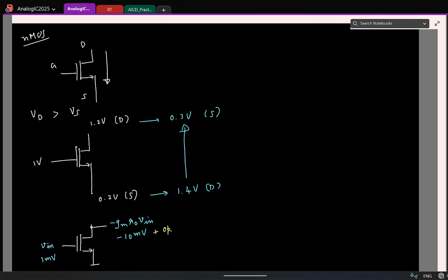That's exactly how we started, right? How are we getting power amplification? This is small signal power amplification, right? From the DC source we are converting things. So just because you see negative voltages in small signal doesn't mean things are going negative. It's just a small signal increment, and you have a DC operating point on top.